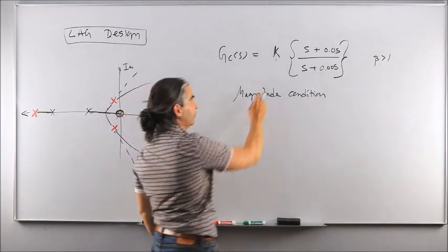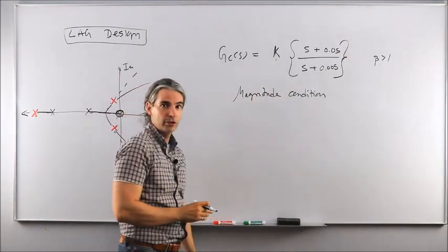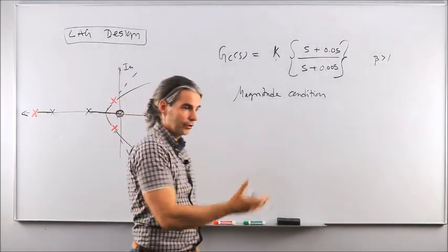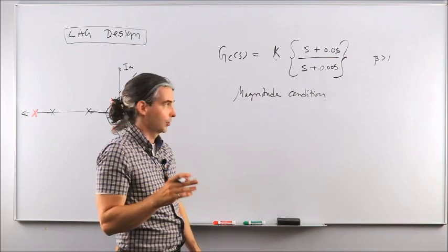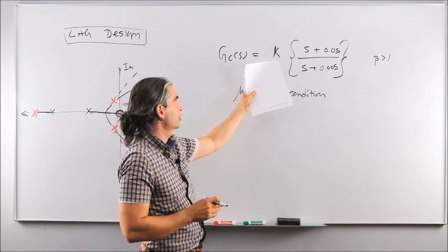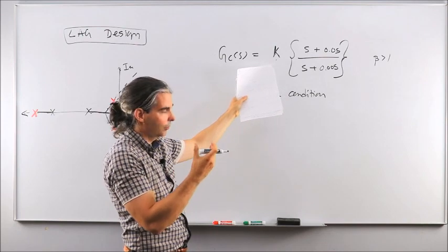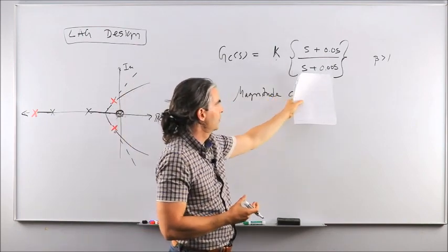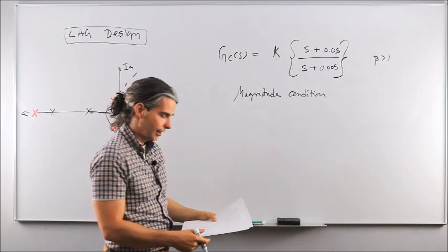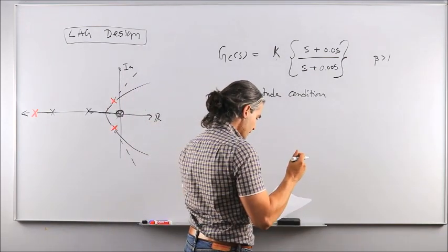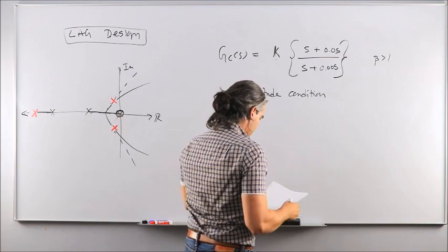If you end up with a gain of 5 here, your calculations, you know you've done something totally wrong. So before handing in your design to your senior engineer, make sure that you rechecked everything, because that gain should always be close to 1. Just by virtue of the philosophy of placing the 0 and the pole of your phase lag compensator in the closed loop root locus, okay?